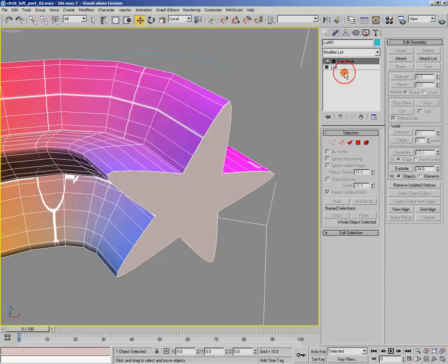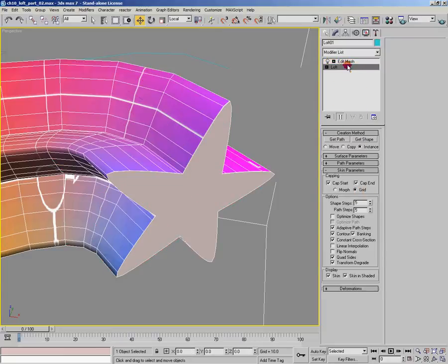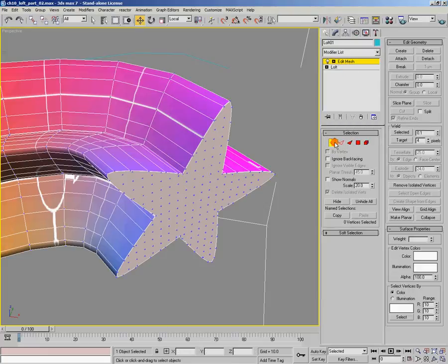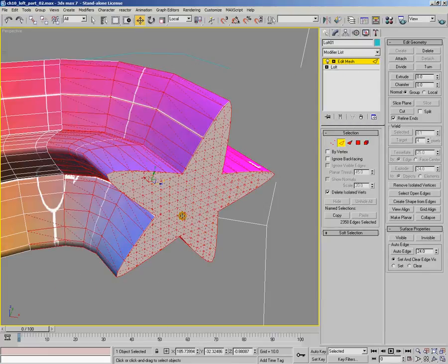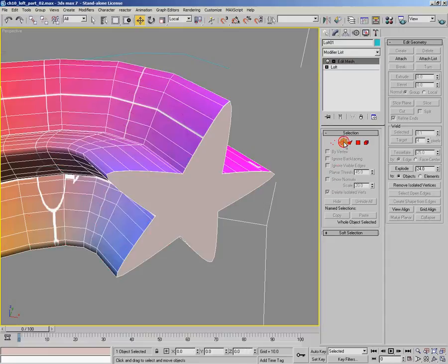But when we go to here and we turn on grid, you can see what it actually does is it creates a kind of grid pattern and then kind of cuts out that shape in a kind of cookie cutter out of that surface. And so this is very dense. Obviously, you can see it has a lot of polygons in. But that density will also mean that it'll deform a lot better if you put some kind of modifier on there. And it may also render a lot better when you render it with those deformations. The long, thin faces in the morph version of the geometry may actually cause some nasty looking artifacts if you deform the surface. So there you go.